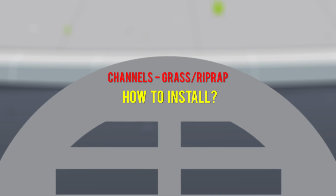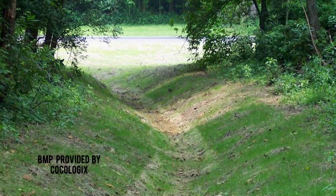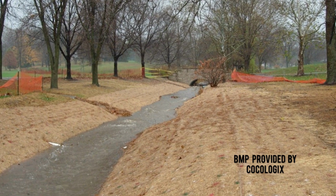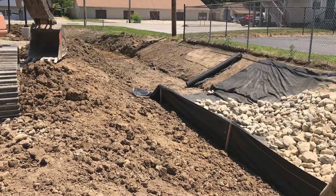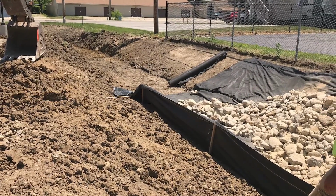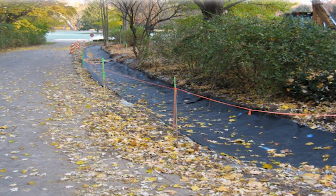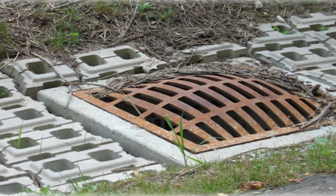How to install. Shape and construct channel as shown in construction plans. For grass channels, stabilize channel with erosion control blankets, turf reinforcement mats, or sod. For riprap channels, place geotextile fabric or aggregate filter medium for stabilization and filtration on the compacted and smoothed foundation. Install riprap. Then for both types of channels, stabilize outlet.